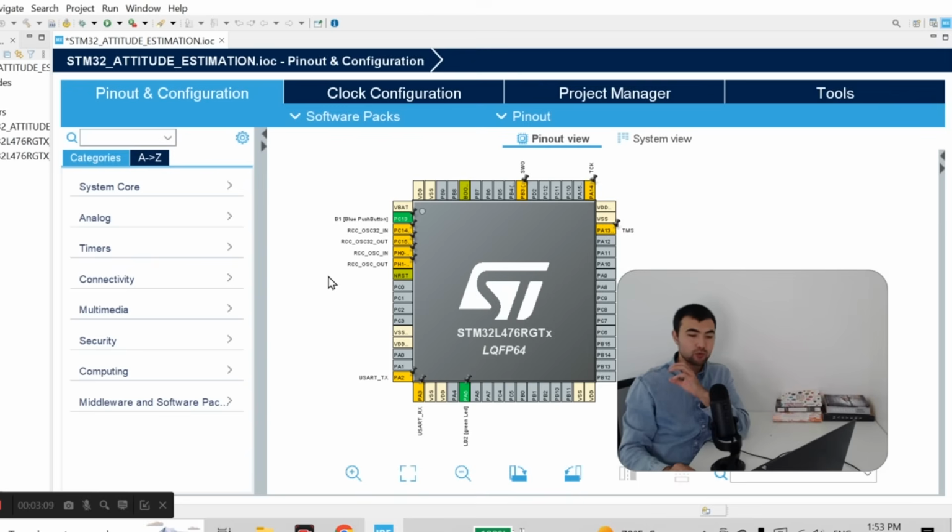However, when using STM32 microcontrollers, we have a tool called Serial Wire Viewer, and this tool allows us to easily implement the printf function. In addition, it has a cool feature which is plotting the variables in real time, so you can see in real time how your data is evolving. I think it is a pretty cool feature and I use it a lot in my projects. So enough words, let's configure Serial Wire Viewer.